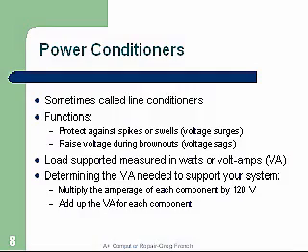Determine the VA needed to support your system. Just multiply the amps of each component by 120 volts. That gives you the power, or the watts, or we call it VA, or volt amps. Add up the volt amps for each component.